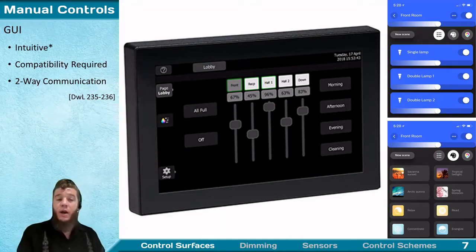The big advantage of these types of systems is they are going to allow you to set up two-way communication. Sometimes scene selectors can do that, but not usually. Usually you're going to want a system more like this, a centralized control system to enable two-way communication. Why do we care? Sensors. Sensors can make your lighting system dramatically more intelligent and more responsive to the needs of your users. So we'll get into those in just a moment.